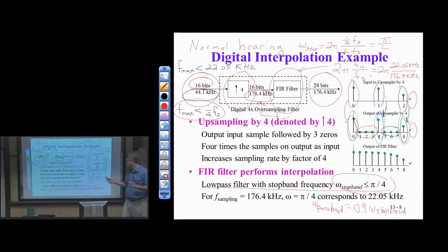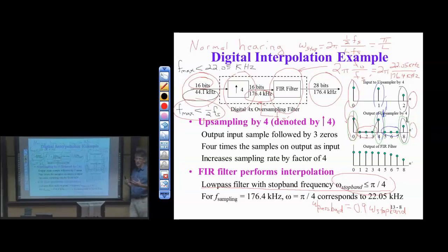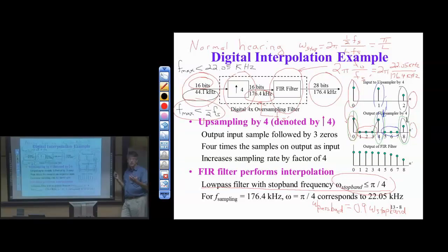There are fewer jumps that you can see here from index 0 to 1, and then from 3 to index 4. It's a sudden jump here. So we've smoothed over those sudden jumps. We've essentially connected the samples that we know by connecting the dots, and the pulse shape, let's say the impulse response of the FIR filter, tells us how we connect those dots. So we could use a truncated sinc impulse response. We could use raised cosine. We could design the FIR filter using Parks-McClellan, Kaiser. You know, pick your favorite method.